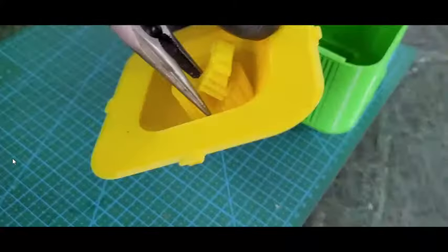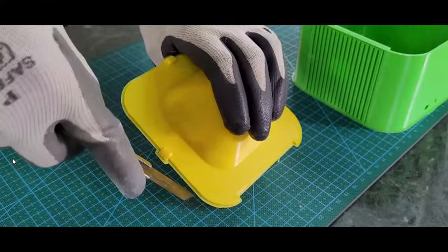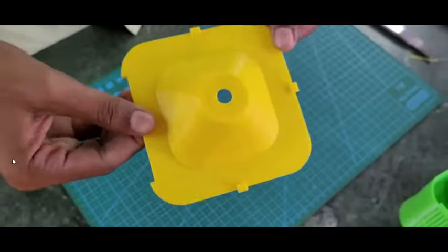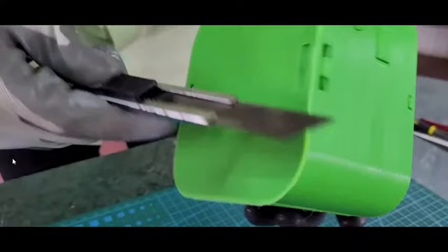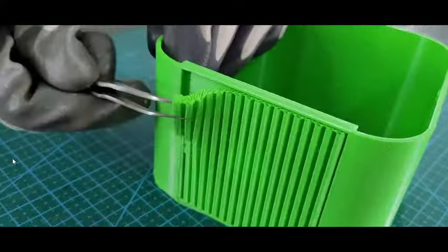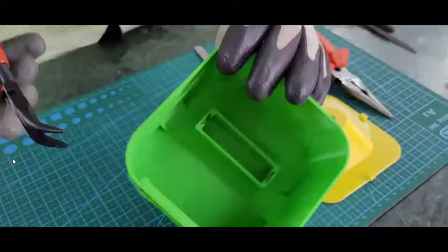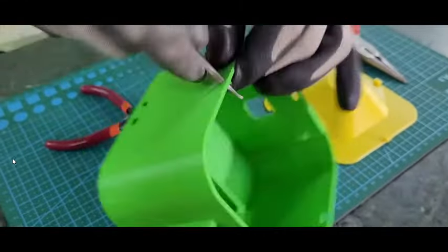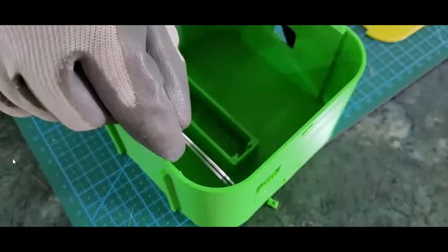Use PPE, remove the support from that LED holder using the long nose plier. Cut the extra fin material alongside the lines using a paper cutter. And same thing you can do with the box, this green box. You can use paper cutter to remove the extra edges and supports. You can remove the supports as well, which are not needed. These are going to be all the supports. Along the edges, there are going to be slots to assemble the yellow LED holder.